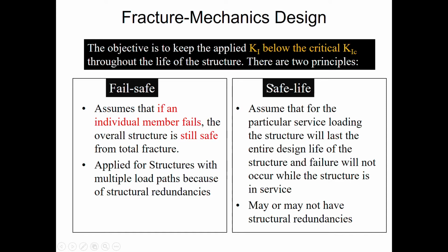Okay, for the other principle, it is the safe life. It assumes that for the particular service loading, the structure will last the entire design life and failure will not occur while the structure is in service. This means that if a failure occurs on that structure, the structure cannot be used anymore. It may or may not have structural redundancies.